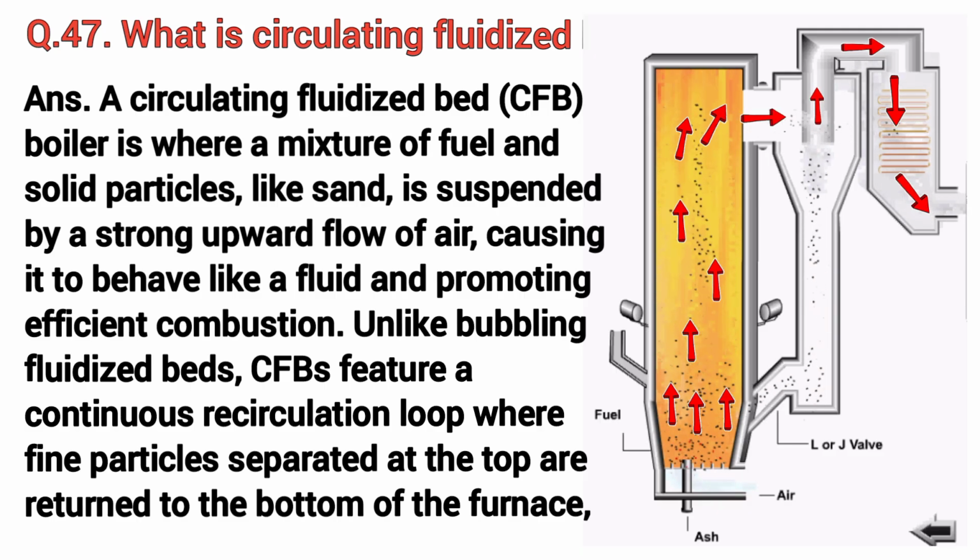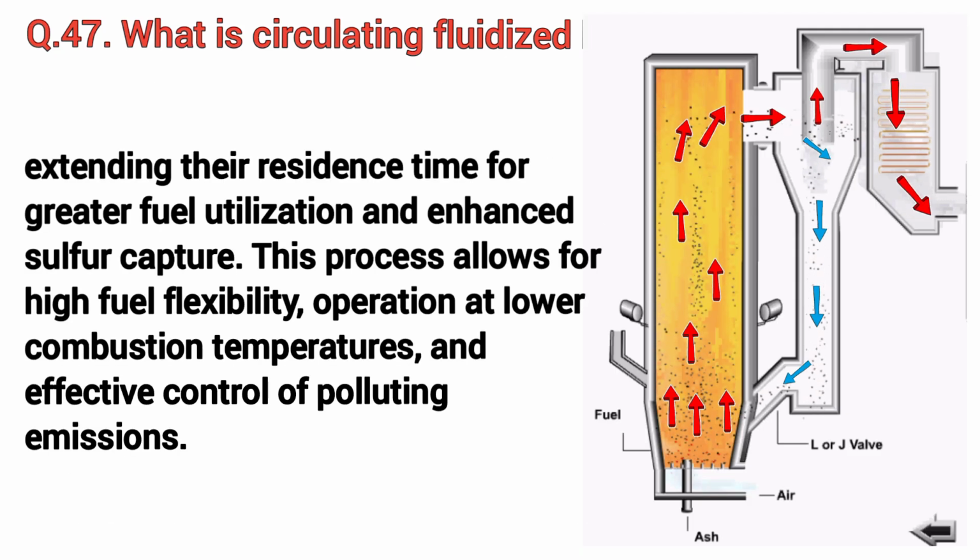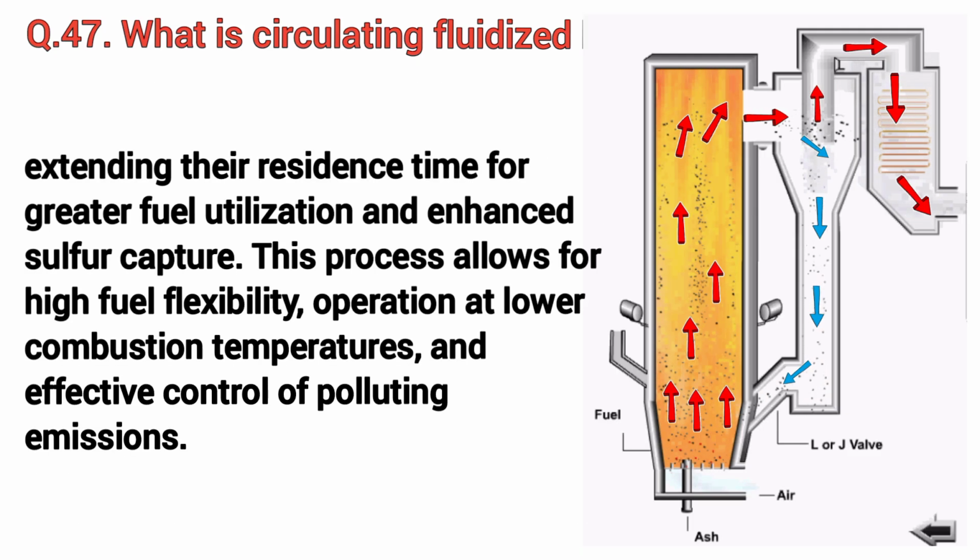Unlike bubbling fluidized beds, CFBs feature a continuous recirculation loop where fine particles separated at the top are returned to the bottom of the furnace, extending their residence time for greater fuel utilization and enhanced sulfur capture. This process allows for high fuel flexibility, operation at lower combustion temperatures, and effective control of polluting emissions.